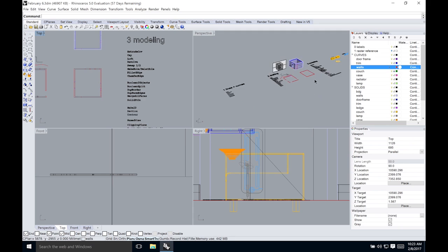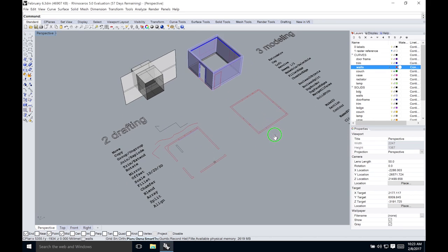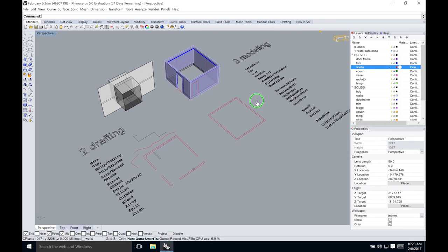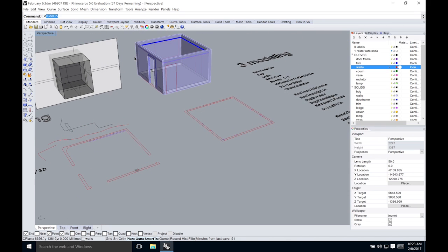as I mentioned, the simplest way to use curves to create 3D geometry is using the extrude command. And if you start typing extrude, you can see that there are a number of different commands in this family of extrude. So the one we will be using is extrude curve, but you can also extrude a surface, which I think for the later tutorials might be something we'll go over.